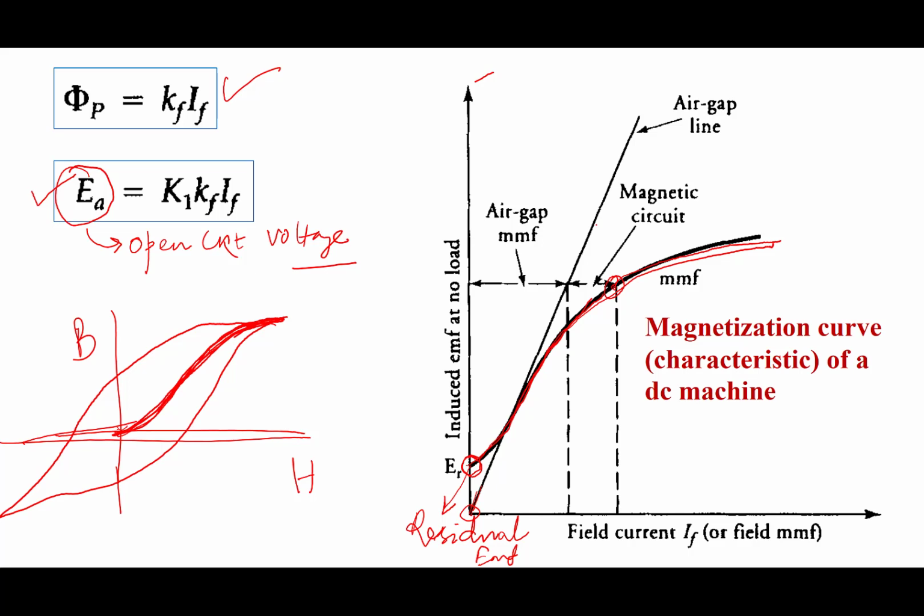So the flux density will reduce if we use air instead of ferromagnetic material. Therefore, even though we are getting a curved characteristic, we prefer ferromagnetic material over air because it will produce more flux density, and in that way it can link more flux to the armature circuit.